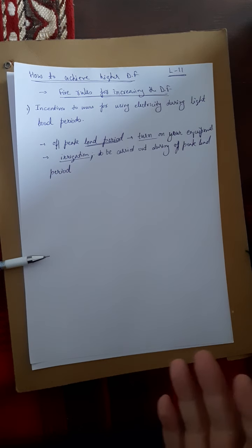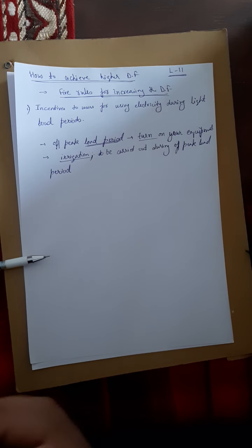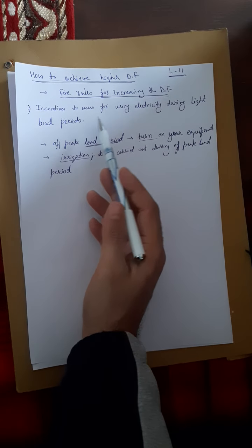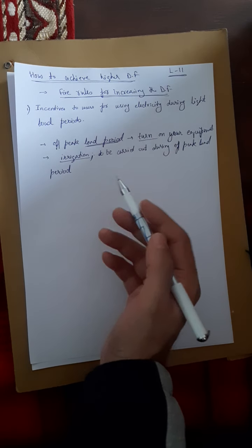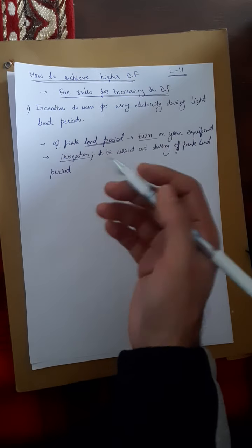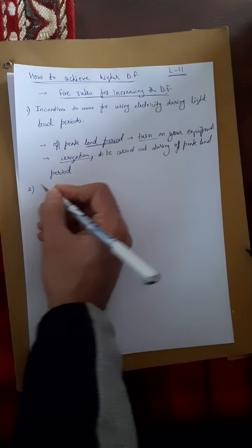On the other hand, the power company which is supplying power, their peak load will reduce. If their peak load reduces, what will happen? They can install a plant of lower capacity. So their investment cost for constructing a power plant will be reduced. So both the power supplier as well as the power consumer will benefit from this. This is the first point: incentives to users for using electricity during light load periods or off-peak load periods. The second point is